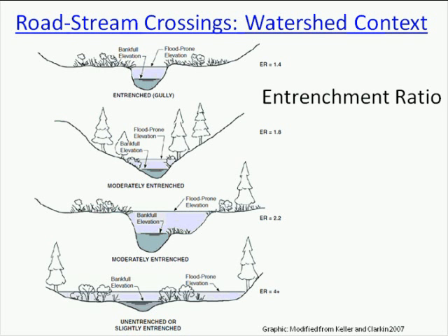In areas where flood-prone width is difficult to determine from site factors, but bank-full is relatively well expressed, the flood-prone width can be estimated by extending the water surface elevation across the floodplain at an elevation equal to twice the maximum bank-full depth.